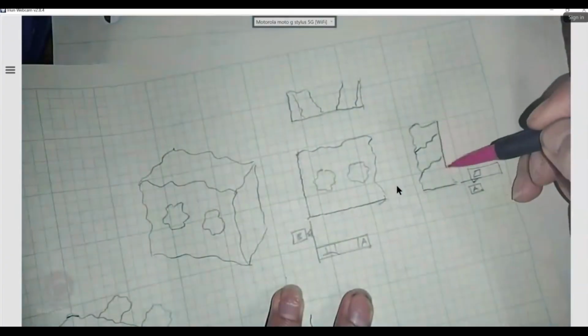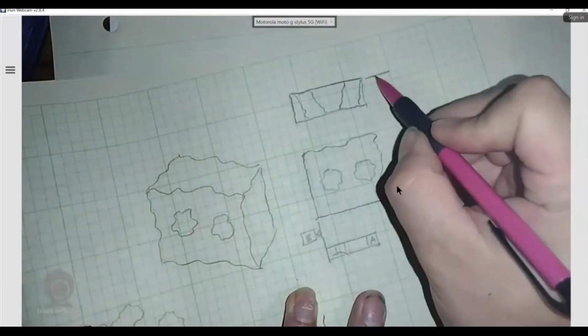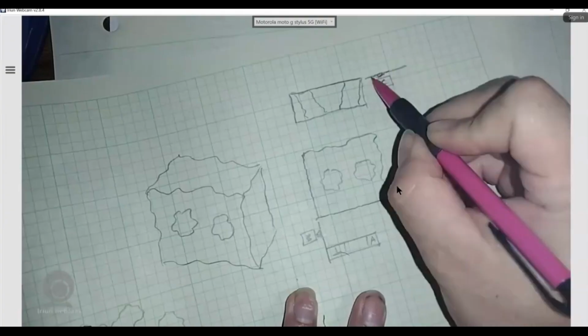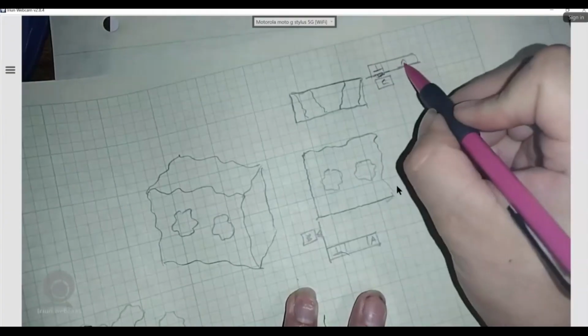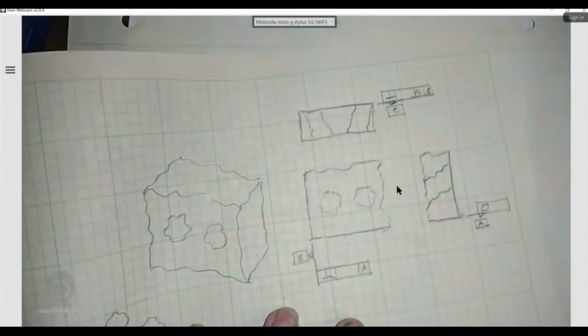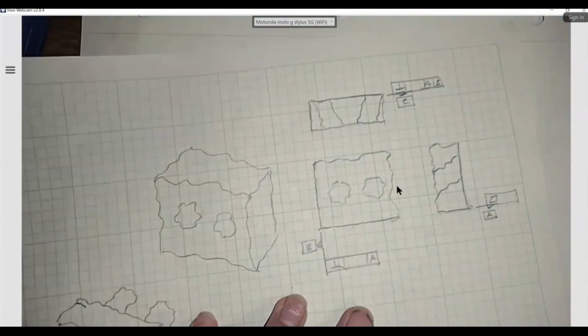Let's refine the back. And let's call that guy datum C and make that guy perpendicular to A and to B. Does that make sense? Now I have a reference frame that I can actually start working with.